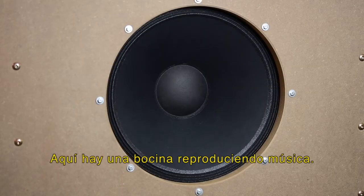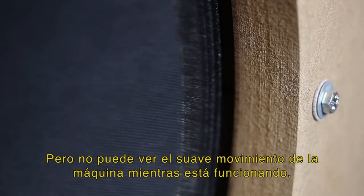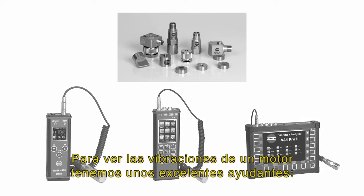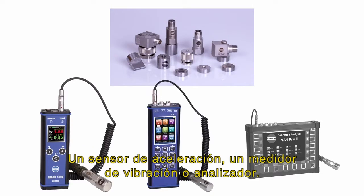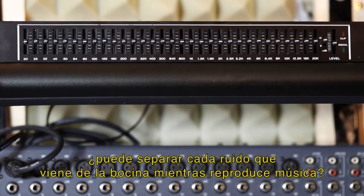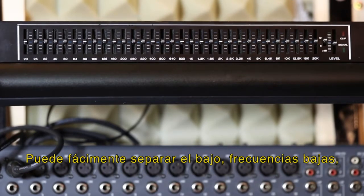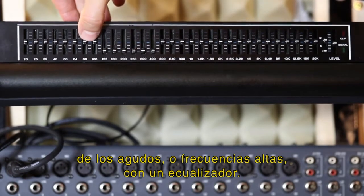Here is the bass speaker while playing some music. You can see the movement of the speaker membrane because the amplitude is high, but you cannot see the small movement of the machine while it is running. To see a motor's vibrations, we've got some excellent helpers today: an acceleration sensor and vibration meter or analyzer. Talking about the speaker again, can you separate each noise which comes from the speaker while playing some music? You can easily separate the bass, low frequencies, from treble or high frequencies with an equalizer.